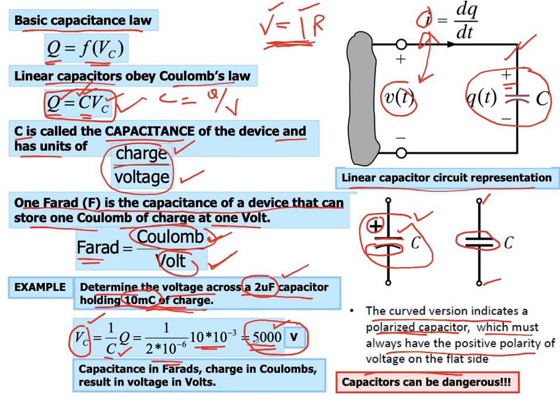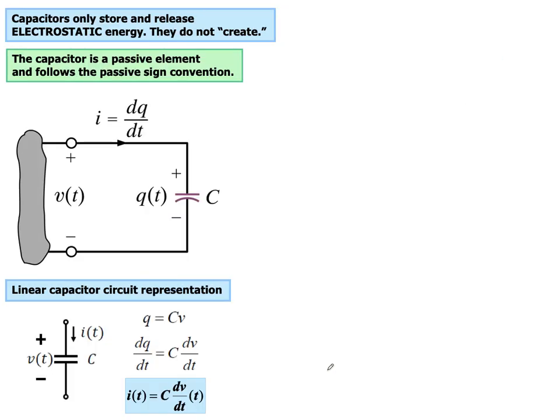So it's always important that whenever you are dealing with capacitors, make sure they are completely discharged before you use them in any experiment. Otherwise, if they are already charged, they would have a huge amount of voltage available at their terminals, and that can give you a shock while handling those capacitors.